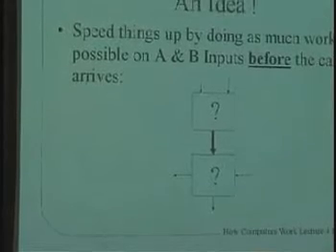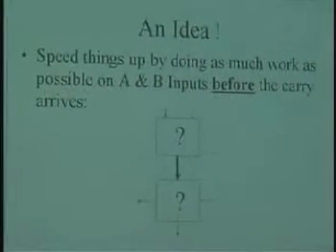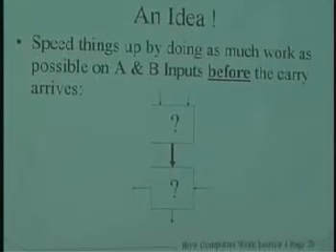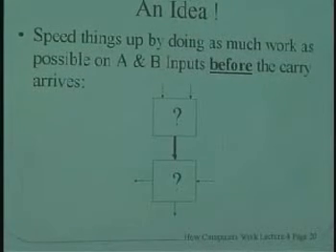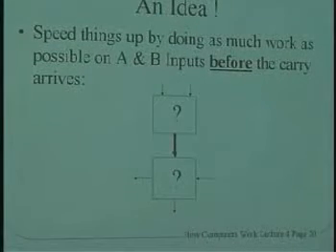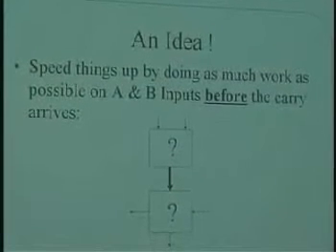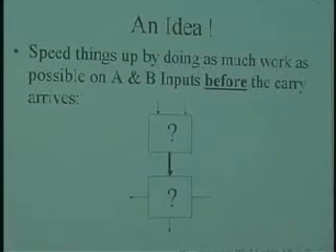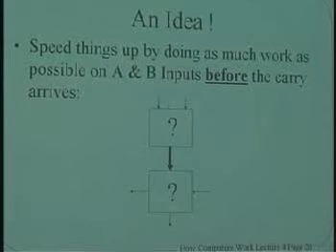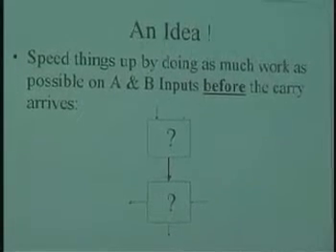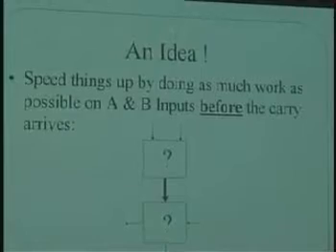So we see how we can implement sum using a parity tree like this, and we see how we can implement the carry out using a sum of products form that we can simplify by using a K-map. But still we're left with an adder structure that's a series chain of these things and kind of slow. So let's talk about exactly what's going on inside of this adder and see if maybe we could speed things up a little bit.